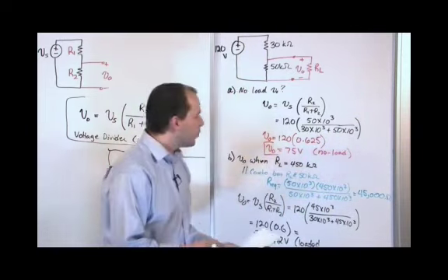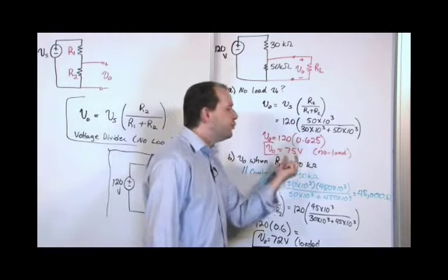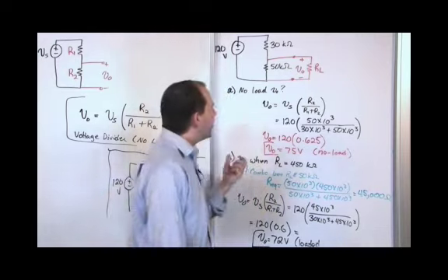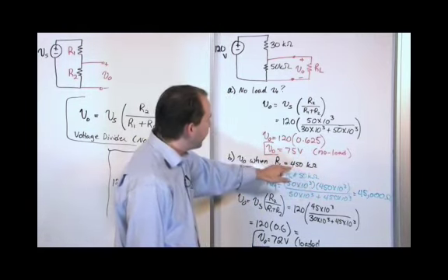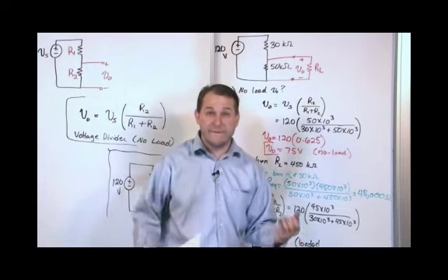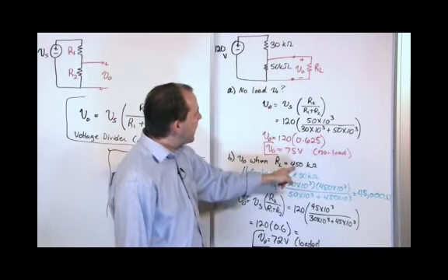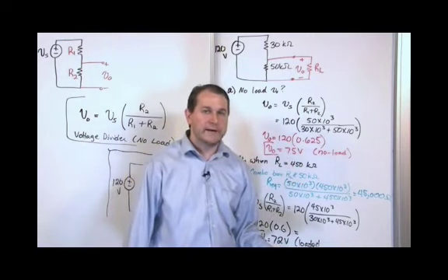What you've done wrong is you've completely ignored the fact that whenever you added your load, you have changed the voltage divider. That's what you've done. And so you can see that because this is still a very large resistor, 450,000 ohms is a very large resistor, even compared to this, whenever you add this guy, it only dips by 3 volts. It only dips by 3 volts.